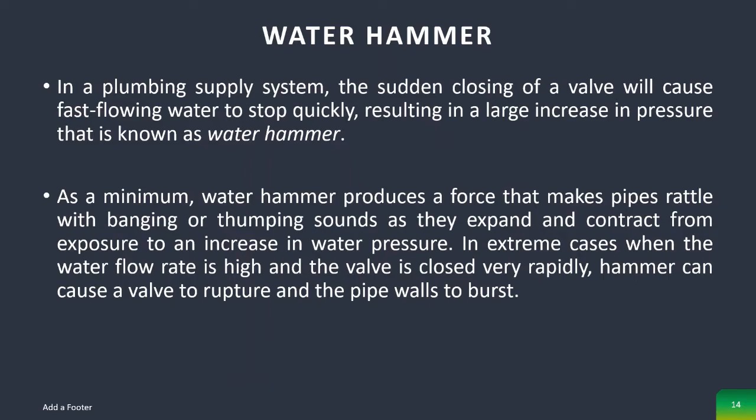Next is water hammer. Water hammer was tackled a while ago in the first topic. So a water hammer. In a plumbing supply system, the sudden closing of a valve will cause fast-flowing water to stop quickly, resulting in a large increase in pressure that is known as water hammer. As a minimum, water hammer produces a force that makes pipes rattle with banging or thumping sounds as they expand and contract from exposure to an increase in water pressure. In extreme cases, when the water flow rate is high and the valve is closed very rapidly, water hammer can cause a valve to rupture and the pipe to burst.